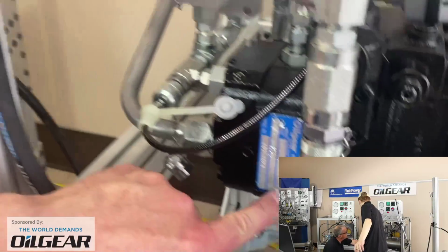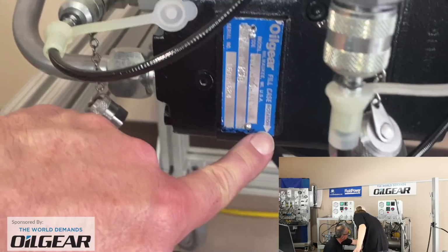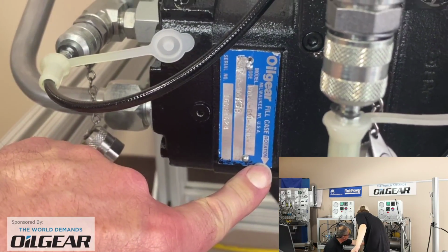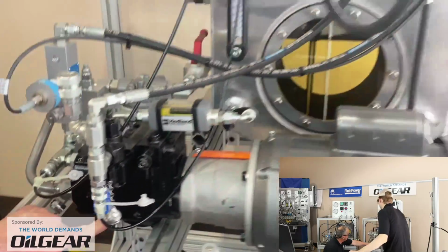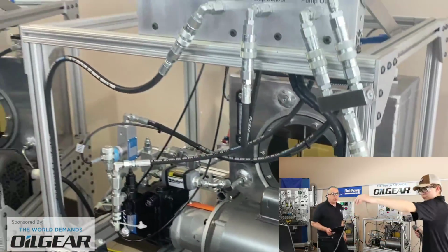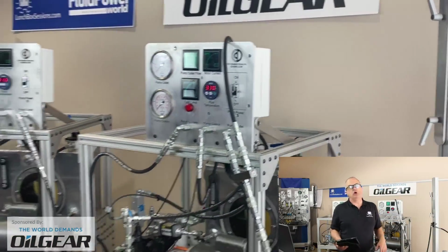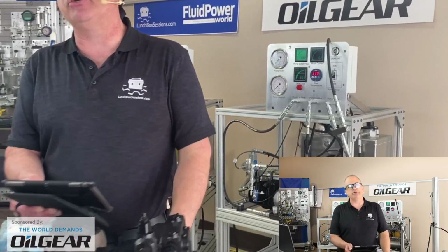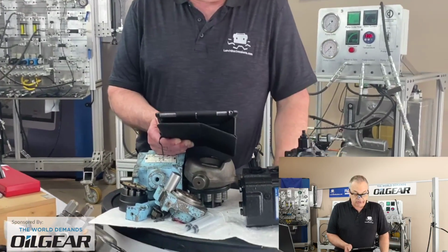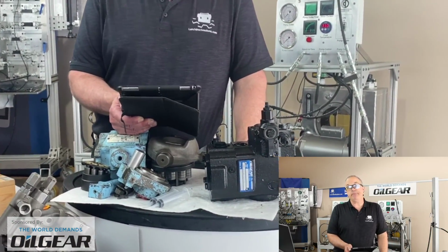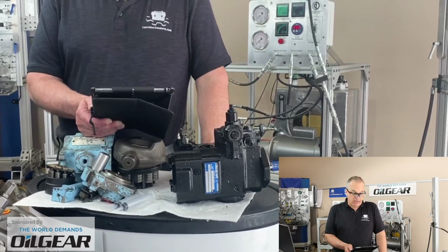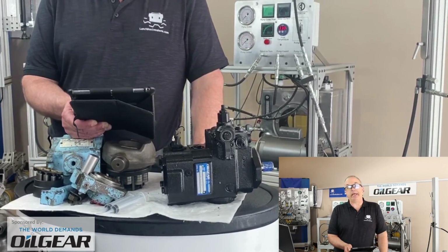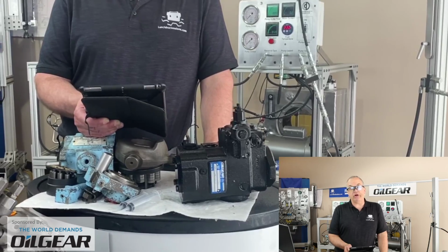Here we see the directional rotation arrow is on the nameplate, so don't let the nameplate get lost or damaged. But it can also, and almost always does, show up in the many letters and numbers of the model code. So take that model code off the nameplate, get the data sheet, and examine it, and that is one of your best ways to verify.